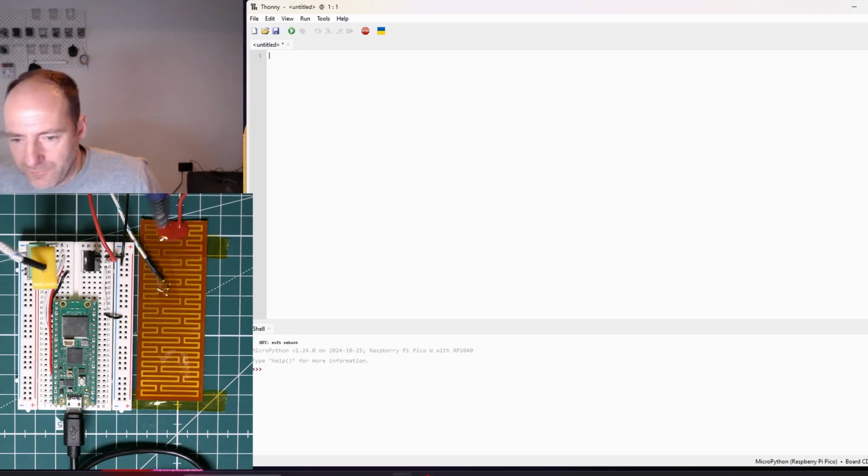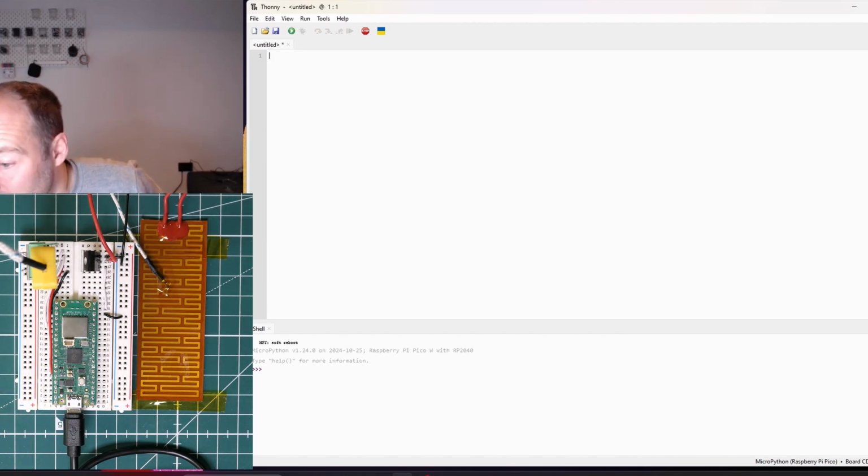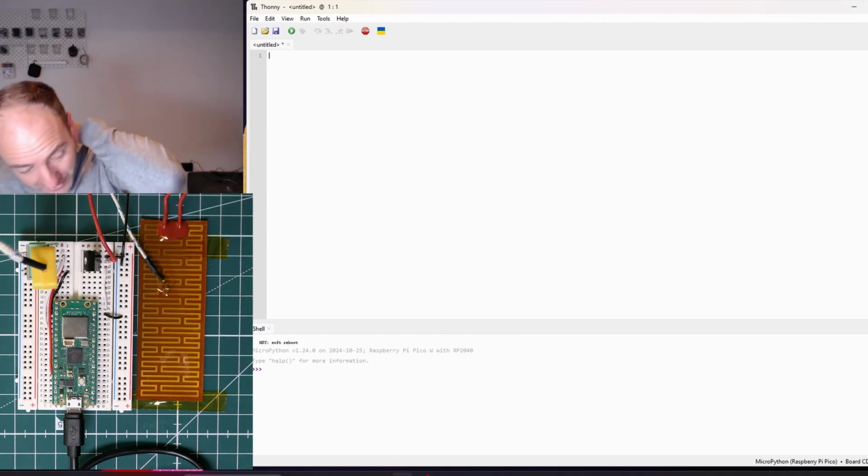So I'm here in Thonny. I've connected my Pi Pico. It's connected to COM9 on my computer, as you can see. And I've actually got my Pi Pico W now, so that's slightly different to what you saw me wiring up a moment ago. A word of advice: don't connect your 12 volt DC power supply to the input of your Pi. It destroys it. I've had to quickly swap that out because I messed up and connected my 12 volt input onto that white wire which goes to the Pi. Destroyed it. Not to worry.